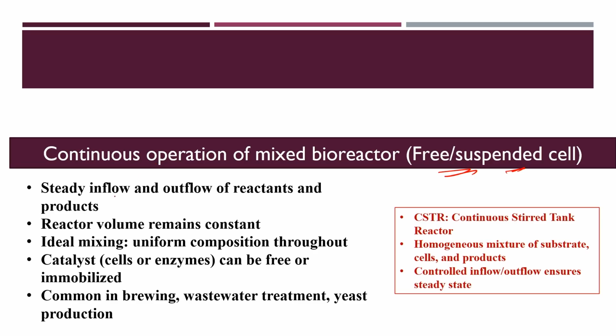So, continuous means we assume steady state flow, steady inflow and outflow of reactant and product. Reactor volume is constant because there is no accumulation, and we are assuming ideal mixing, uniform composition throughout the bioreactor. The catalyst, it may be the cell or enzyme, can be free or immobilized, and the common applications for CSTR are in the brewing industry, wastewater treatment and yeast production.